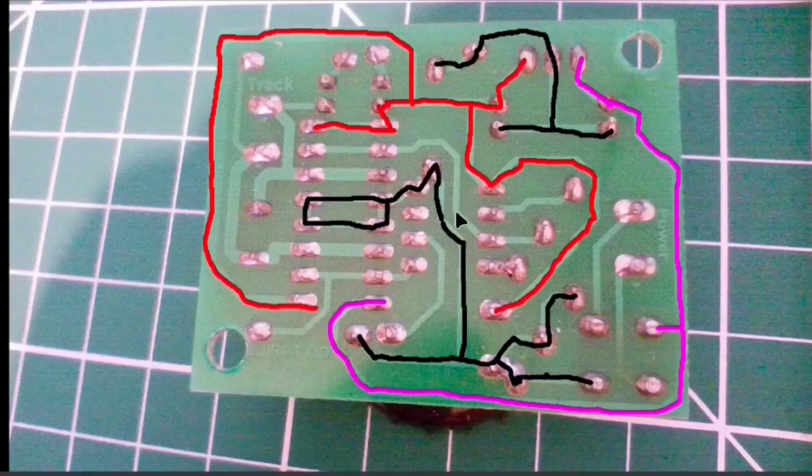Now I have done some work with PIC microprocessors in the past, and by coincidence I was looking at a PIC 12F675 about a year before I came across this circuit, so I'm fairly sure that was a, well, I became fairly sure that was a PIC 12F675. So having established that, I checked the data sheet for the 675, and the inputs match. The 5 volt and 0 volt inputs match.